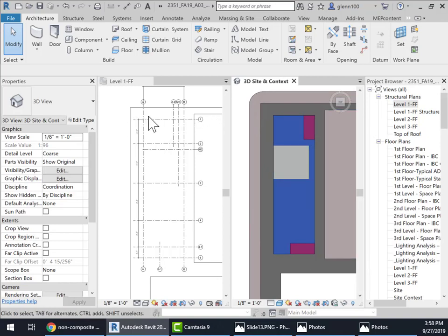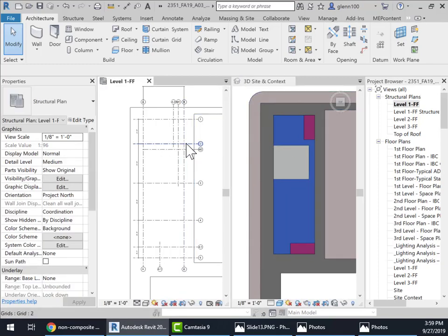And so we have 1 is this line right here. There's going to be a frame right here. We're going to run our frames across this way. So our main girders are going to be in this direction like this. And then we're going to connect it this way with a series of beams and trusses. You'll see I've got right here at the edge of this stairwell, that grid line right there, which represents the end of that stair. We need structure all the way around, our columns all the way around these stairs.